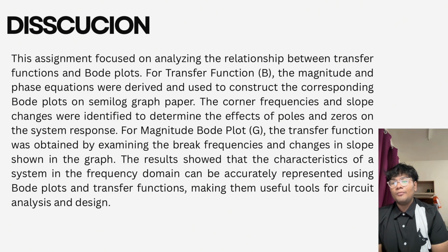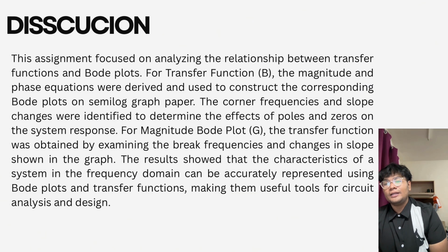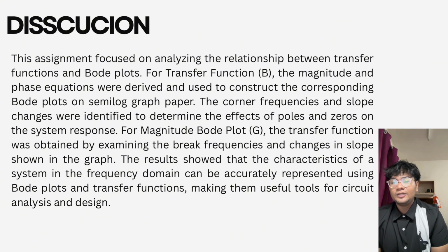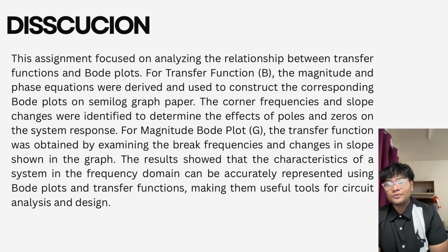For the magnitude Bode plot, we chose G. The transfer function was obtained by examining the break frequencies and changes in slope shown in the graph. The results show that the characteristics of a system in the frequency domain can be accurately represented using Bode plots and transfer functions, making them useful tools for circuit analysis and design.